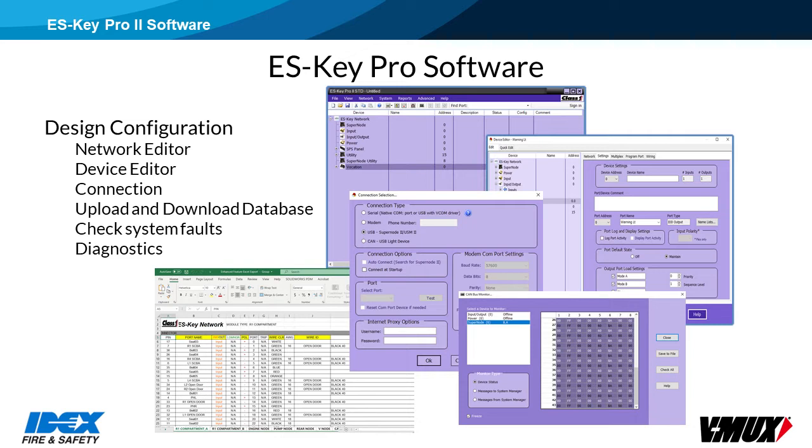The connection type field allows the user to choose a serial, a modem or a USB connection. Each time the user changes between serial, modem and USB, the system is scanned for available ports of the given type. If a COM port or modem is currently in use by another application, it will not appear as a selection for configuration. If the intention is to use an external modem, ensure that it is powered on and connected to the PC before selecting modem or it will not appear as a selection. If a USB is used, the port will be found automatically after selecting the USB connection type.